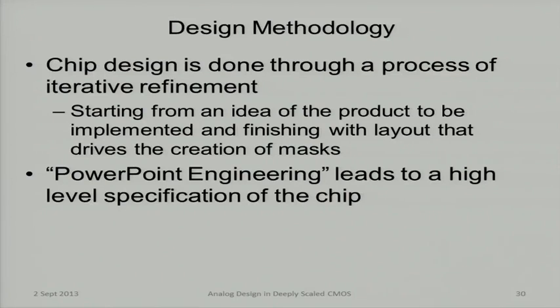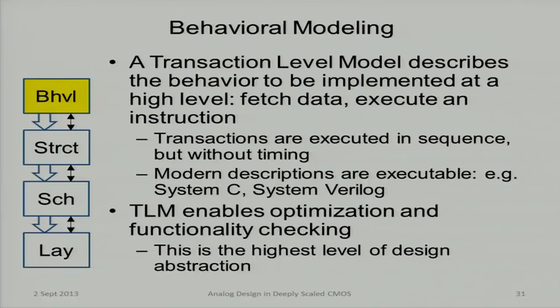And often you start with PowerPoint engineering, some concept that is not executable, just written down, but that provides your initial description. But then we tend to go through this level of description where we go from behavioral to structural to schematic to layout. And this actually applies to analog and digital, although the details differ. In a digital realm, I'll have a transaction level model for my behavioral model, where I just describe the sequence of things that happen.